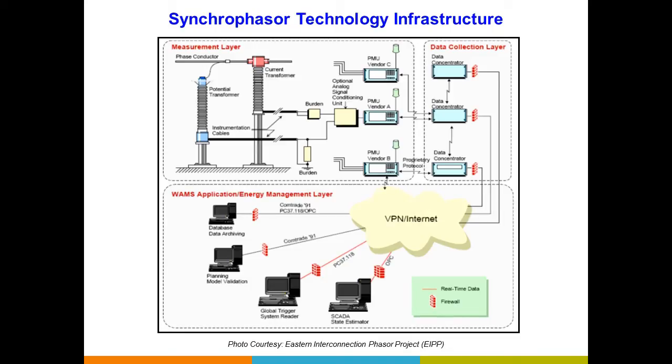The state estimation algorithm in the EMS might need synchrophasor data. There can be stability algorithms as well running in the EMS which will need synchrophasor data to see if the system is stable or not, or if some proper control actions need to be taken to make it the way the operators want it to be. So this is the typical synchrophasor technology infrastructure.